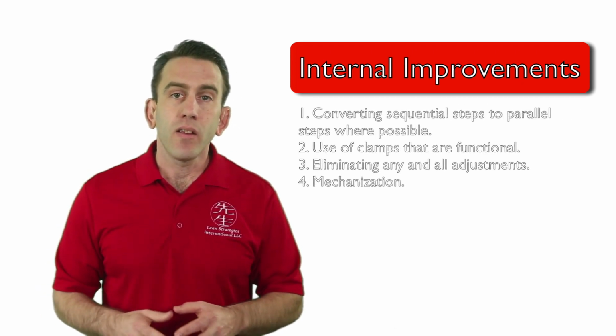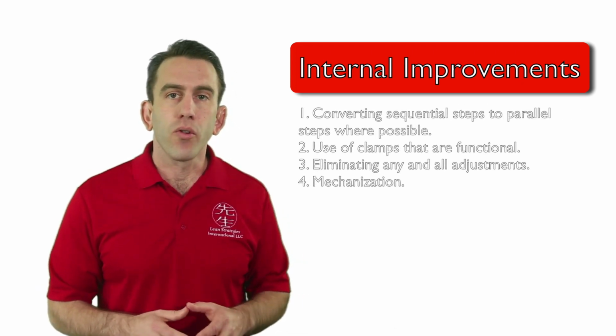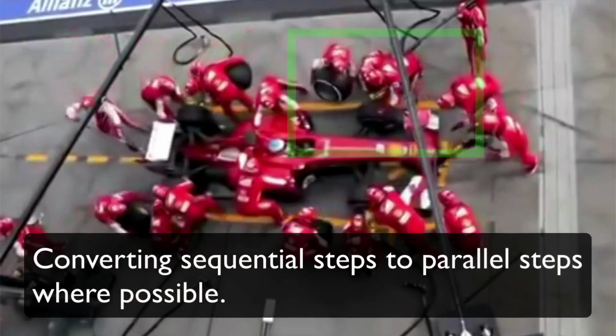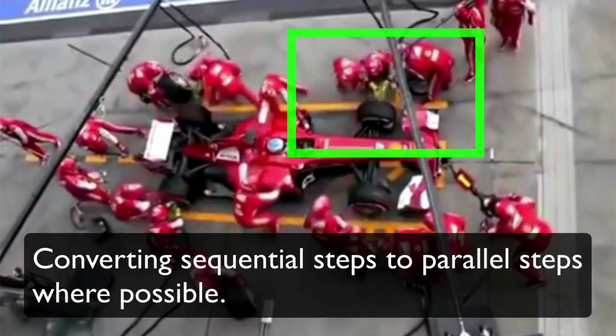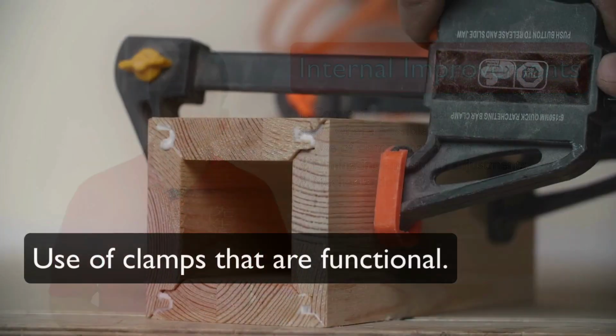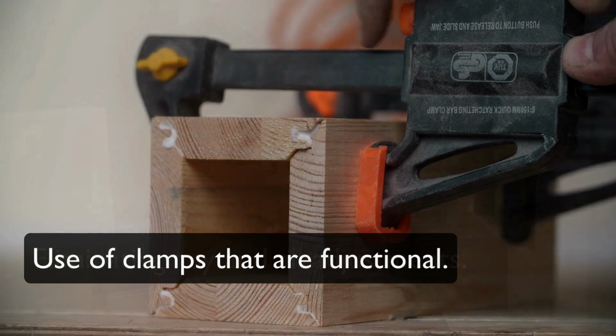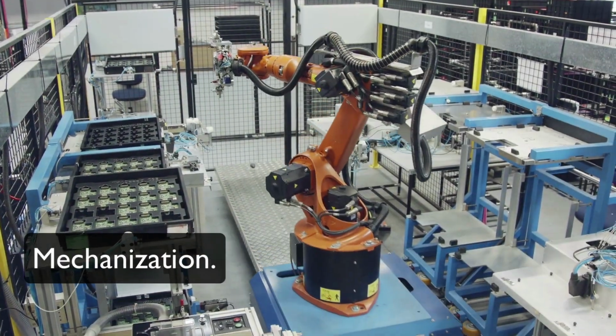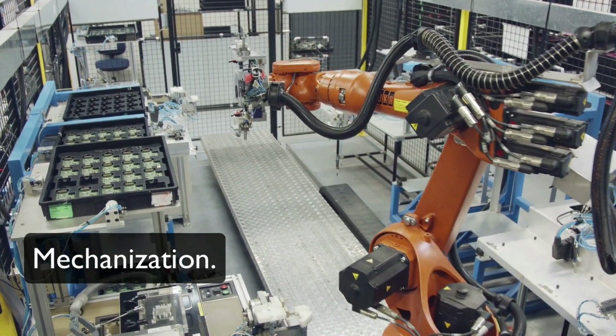The 4 techniques that can further reduce your setup or changeover times are: first, converting sequential steps to parallel steps where possible. Second, use of clamps that are functional. Third, eliminating any and all adjustments, and last but not least, mechanization.